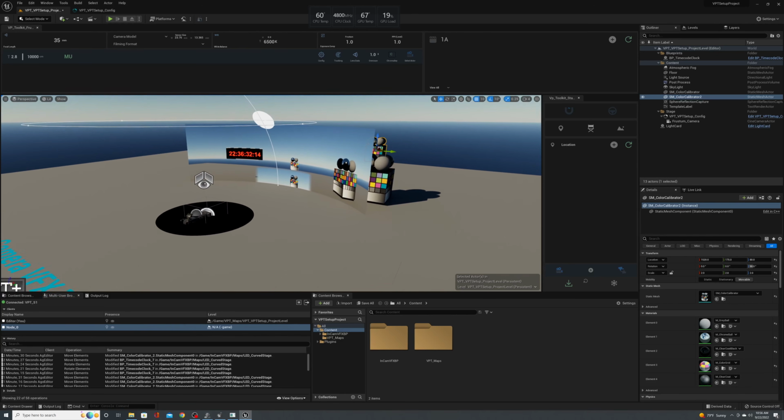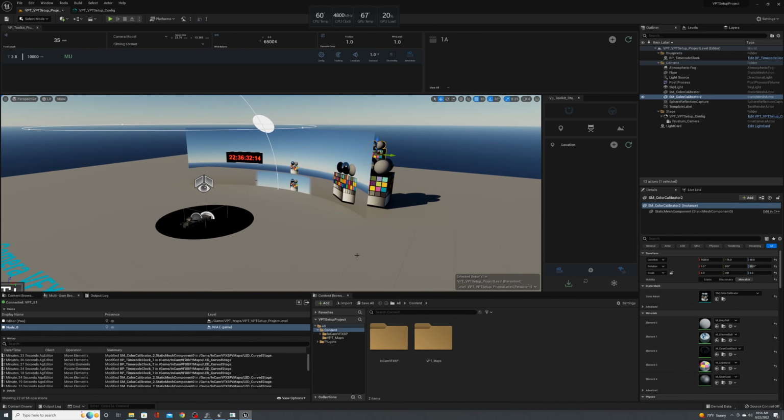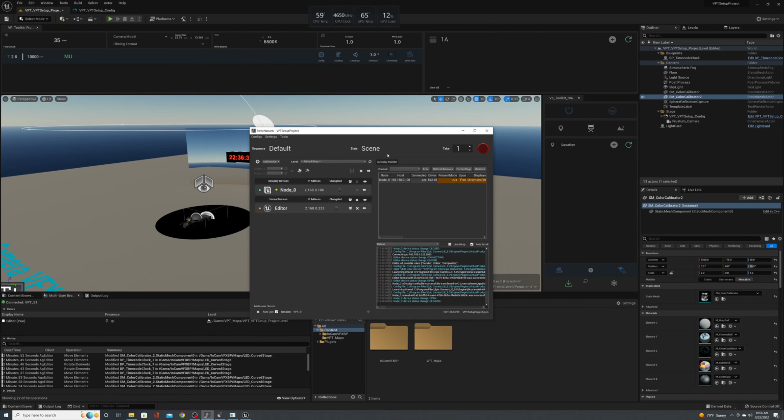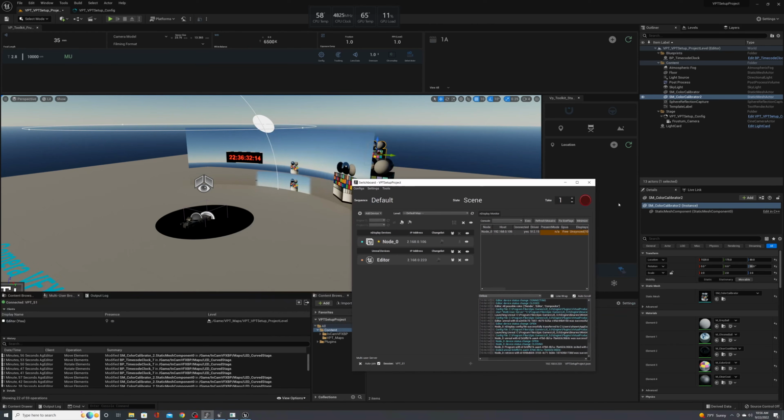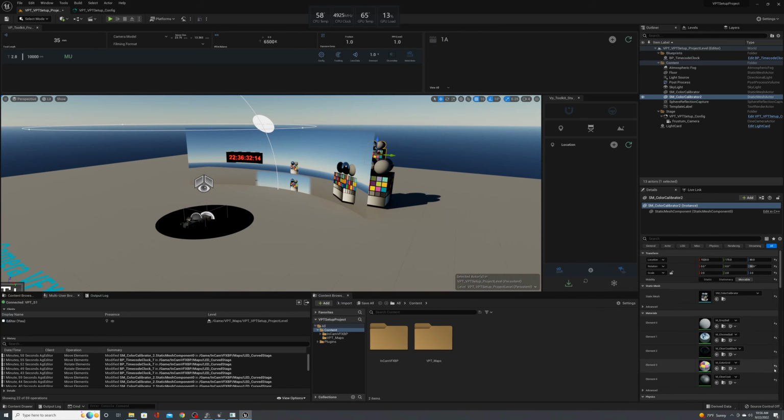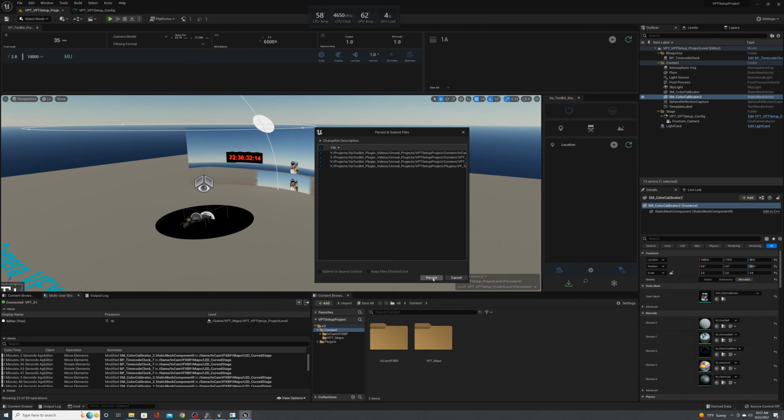So now once you've made any changes to your level, there's a couple ways that you can do this. Since we are running a single project, running to both machines over our network shared drive, we want to close our nDisplay projection on our render node, and then go to source control on your bottom right here, and then persist session changes.